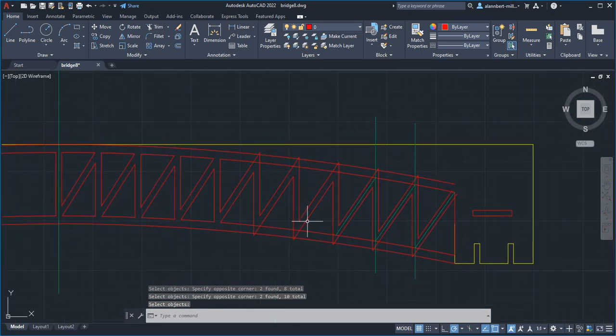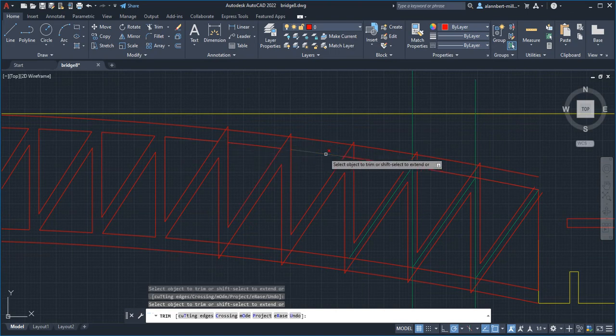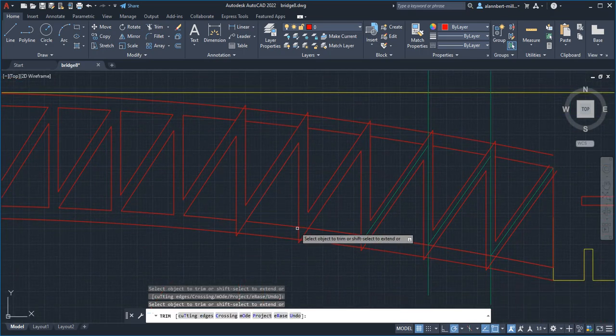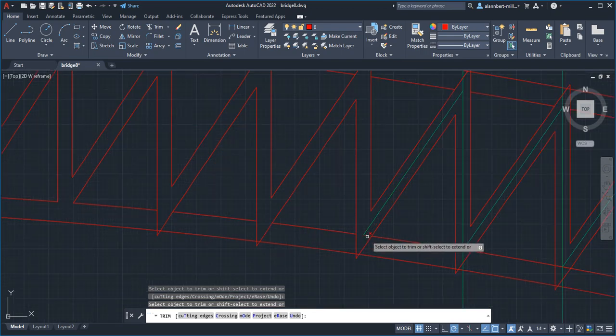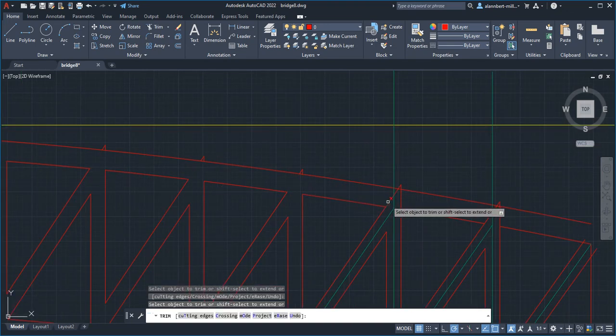Once you're finished, you're going to mirror. So let's just finish this one. I'm going to trim, trim, open it up by trimming. And then you're going to also trim the MLINEs that you created. Trim here, here. You want to trim first before you do the mirror because if you don't, then you're going to double your work. You want to do less work, not more work.